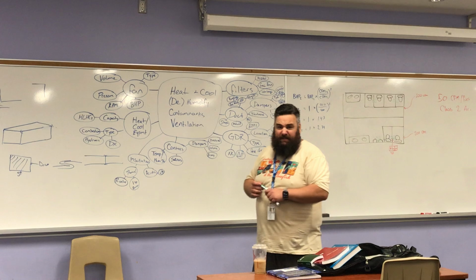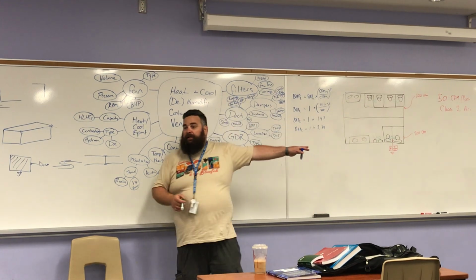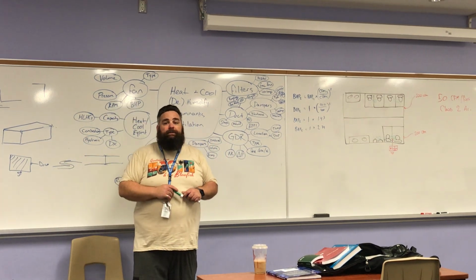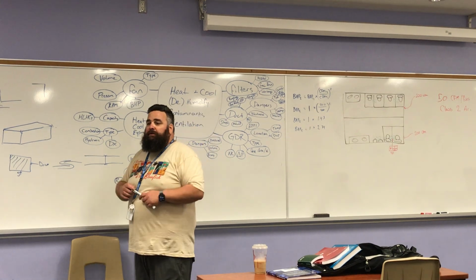At least 10 feet from the intake, but what are our options? I know you don't have a whole floor plan here, so you don't know what the rest of the building is, so just spitball. Roof? Sorry? Roof? Roof, go through the roof. Wall. What else? Yeah, side. Sorry? The side or the wall. Side discharge. What are the consequences of that?